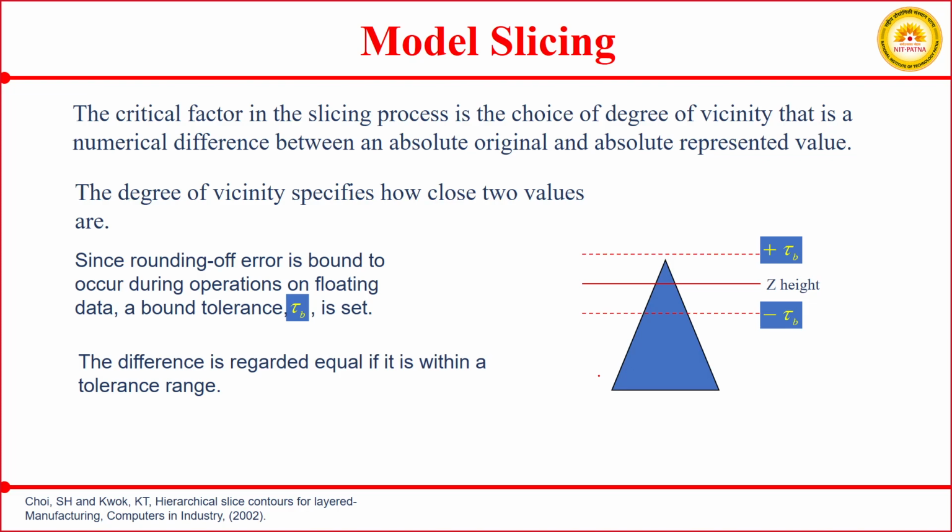Okay, so during this slicing, in any slicing plane or cutting plane, you can set a tolerance limit, like some value such as 0.2 micrometer or something, depending upon the size of your triangular facets. Suppose, let us not discuss units, let us say it is 10 units.